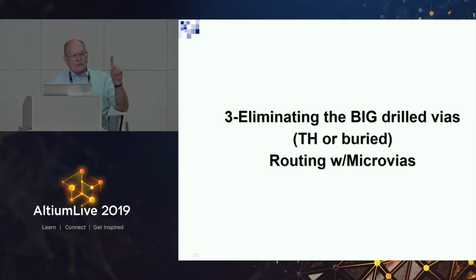Once you have one microvia, you incur a step charge. And then, unlike drilled holes, you could do 200,000, same price as 20. Because at 600 a second, they go really fast. The only problem is that in your mind, you've been thinking mechanical, we want to minimize the number of holes. That's true for mechanical drilling. For laser drilling, don't worry about minimizing. They're so cheap and they're so fast. If you want to use 10 times as many, use 10 times as many. They're very small. They're not going to cost you anything.